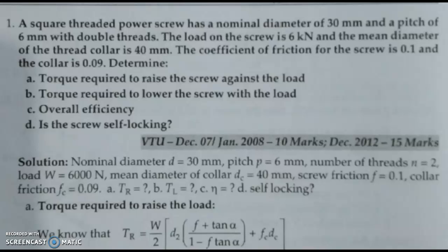Determine, first, the torque required to raise the screw against the load. Second, the torque required to lower the screw with the load. Third, the overall efficiency. And fourth, whether the screw is self-locking.